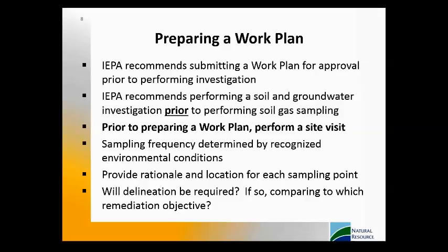When speaking with the IEPA, they actually reviewed my presentation. They recommend that you perform a soil and groundwater investigation first, before you develop a soil gas investigation, if necessary at all. From there you can screen out where your hot spots are and also what your contaminants of concern are. The next bullet is: prior to preparing a work plan, perform a site visit.